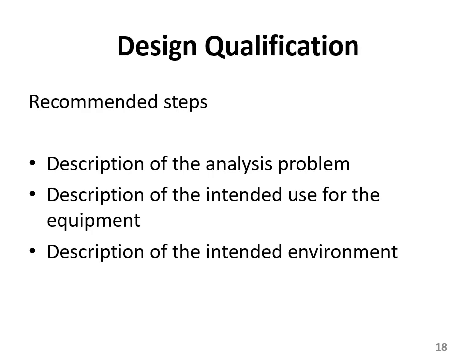There are a few steps which, if you follow them while doing the design qualification, help you a lot, right? What is helpful is to just describe the analysis problem. If you're getting some problem, describe it. Describe the intended use of the equipment. If you are using an equipment, what is the intended use? Design it properly. What is the intended environment? So describe the intended environment, the environment where you're going to use the machine. That is also important. Describe it.